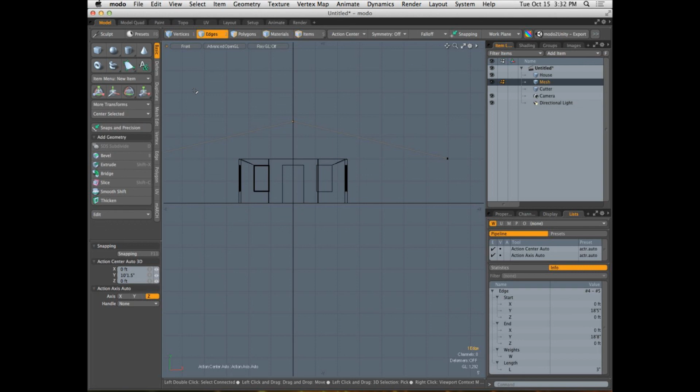Now, is that an extruded shape, or is it a two-dimensional polygon? It's extruded, yes. Deselect that then. I had a two-dimensional shape, and I was just slicing it right down the center. So I deselected it. Perfect. Are you looking at it from the front still? Okay, now go ahead and fire off the slice, and then control. What's this line? I think it's trying to slice horizontally instead of vertically. If you slice right down, there we go. Is that the center? That's where the purple line is, where the slice is going to go.